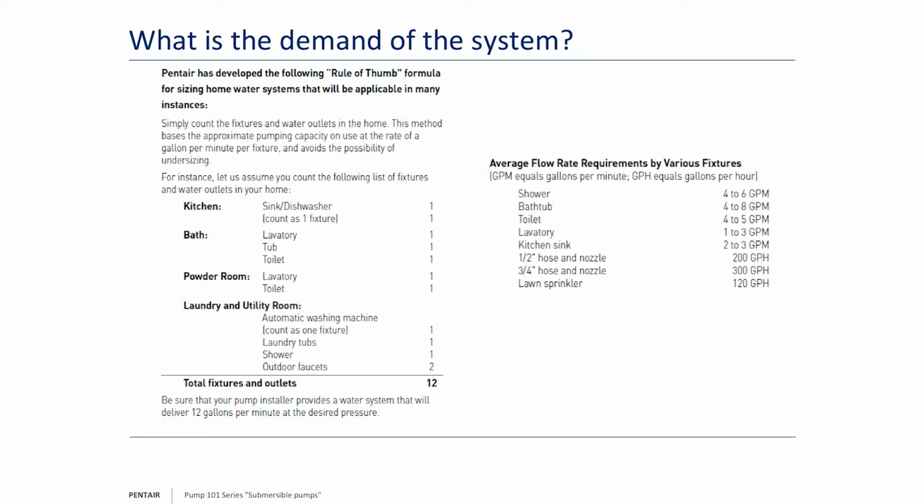If the well only produces a half a gallon per minute, a lot of people say, well, why would you even drill a well that produces a half a gallon per minute? A good example is out on the East Coast. They'll drill wells 700, 800, 900 feet, 6 to 8 inch casings, producing only half a gallon per minute, but the water table rises to say 50 feet, maybe 100 feet to the surface.